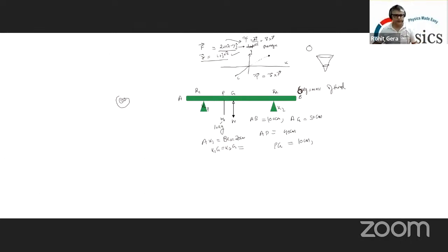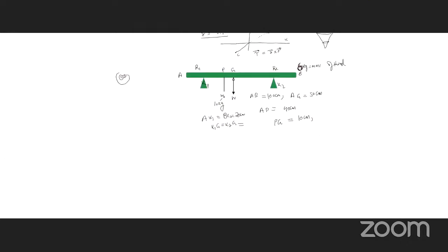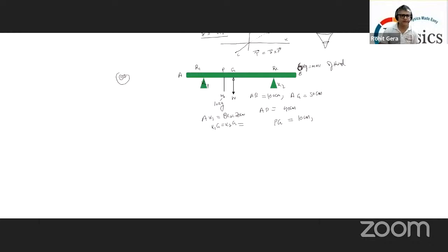Okay. Any questions written? अरे सर बस एक मिनट लिख रहा हूँ. So you know the normal reactions, right? So one normal reaction. So दो vertically upward और दो downward weight है. Reactions are upward. So vertical motion तो balanced है, rod उड़ के नहीं गई है. So R1 plus R2 has to be equal to the weight of the rod and the extra weight at P. Weight of the rod is 6 kg, right? So R1 plus R2 is equal to 16g.